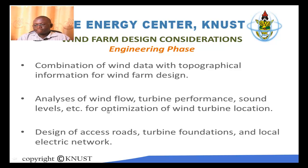Then the wind flow regime over the whole terrain is also analyzed, and then the wind turbine performance: if the wind turbine is placed there in a particular wind regime, how much power is it going to generate and all that. So all these analyses are done at this stage, the sound levels, how much noise will be produced, is the noise too much or is it within acceptable levels and all that. You need to determine all those things at the engineering phase.